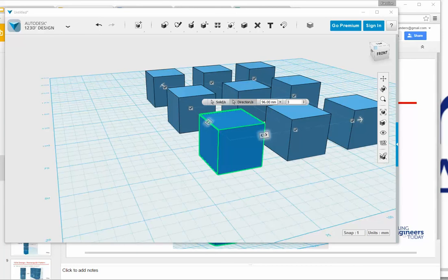So that said, if you have gotten a solid hang on the pattern design, the linear pattern, rectangular pattern, give the circular pattern a try. It behaves a little bit differently, but instead of it being linear, as in along this work plane, it will work in a circular pattern. So if this grid were of circles, that's how the circular pattern would behave. It'll rotate your object around an axis or an edge or whatever you set it to rotate about.